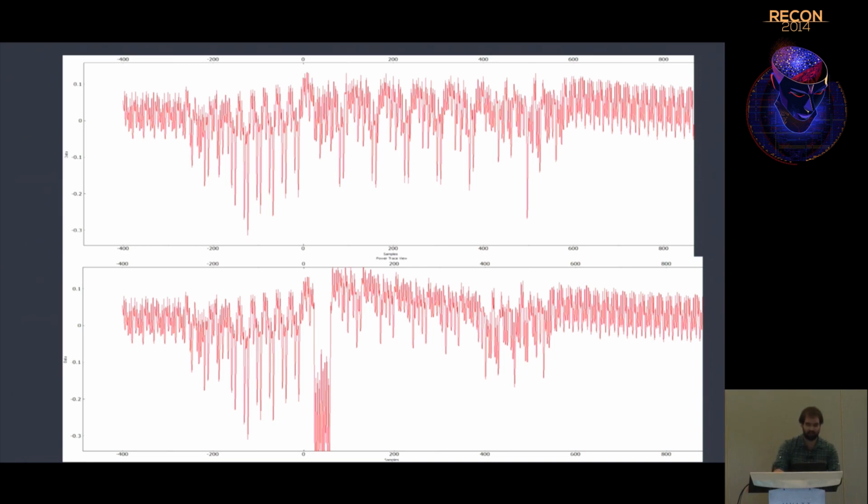So you can see, for example, that some of these loops here, this is actually the while loop going over that 5 or 6 times through the counter. So you can insert a glitch trigger on something like here, which is, I don't know, some initialization code, and then insert the glitch occurring, this large power consumption dip. So in real life, you'd use something like that, but for reliability reasons, I have it set up to use an I/O line.